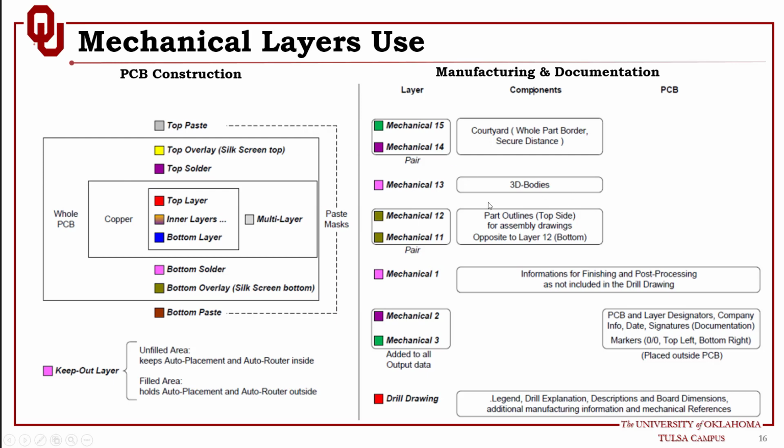Basically, when you create a 3D model for the PCB, you are helping the assembly house to do the assembly, because they have a 3D perspective of that board, and also you are helping the mechanical engineer to design an enclosure, because the mechanical engineer has a perspective about the dimensions of the board, etc. The assembly outlines also will help the assembly process, and so on.